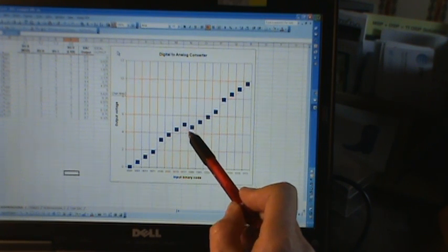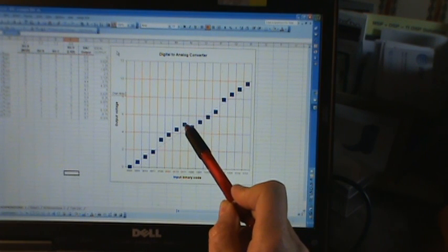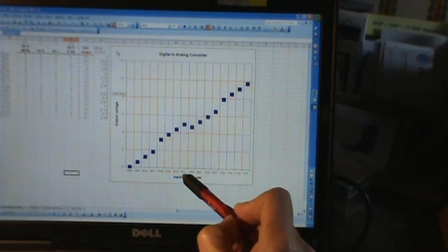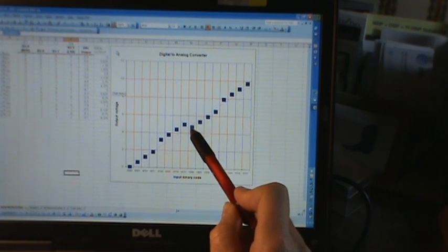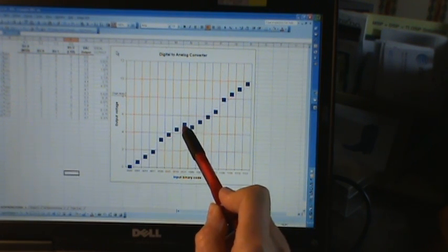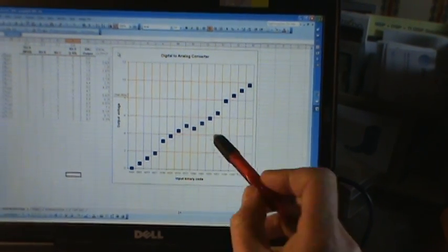And then it continues on, then I add 0.6, then I add 1.2, then I add 1.8, and then here's where I recognize the non-monotonic aspect of it, because I'm turning off all 3 of the lower significant bits, and I'm turning on for the first time my most significant bit. And I see the output value drops from, what was it in the table, 5.0 down to 4.7.